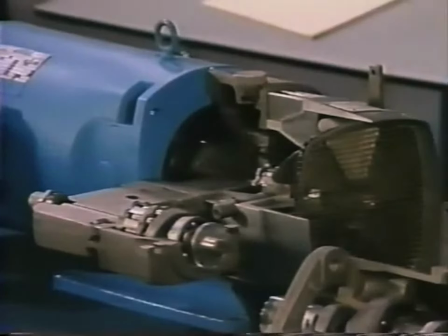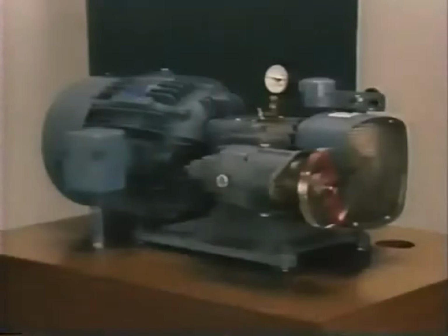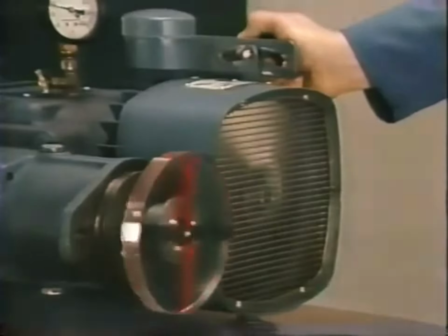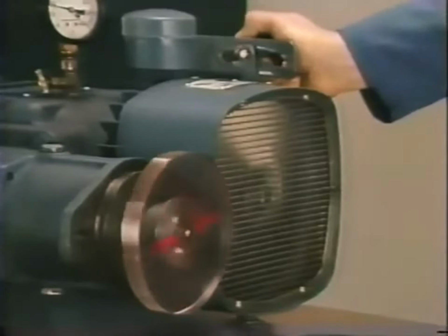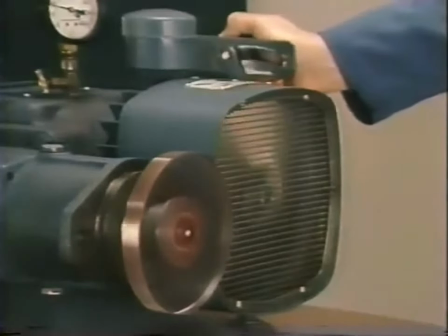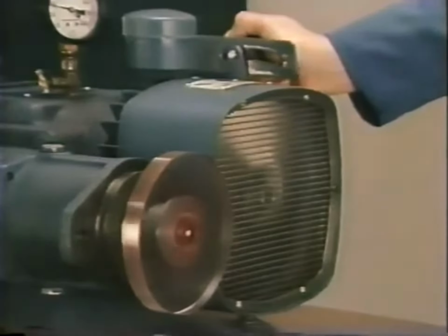Now let's move from our cutaway to a working unit. Right now, the electric motor and pump are turning at 1800 RPM, but there is no movement of the motor shaft. Actually, we couldn't move it if we tried, because the pump yoke is centered, and its pistons can't move in or out of their bores. Moving the lever off-center causes the motor to rotate slowly. The more we move the lever, the faster the motor runs. How fast the lever is moved determines the rate of acceleration and deceleration of the motor, and of course, crossing center will make it reverse.